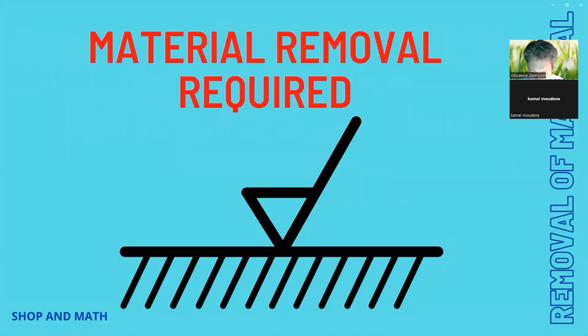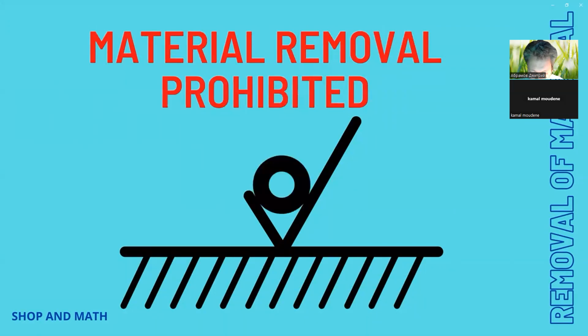Material removal required. This symbol is usually accompanied by other symbols such as lay. Material removal prohibited. There are multiple reasons why they use this symbol, but one of the more popular ones is that the surface is a datum for internal reference dimension.